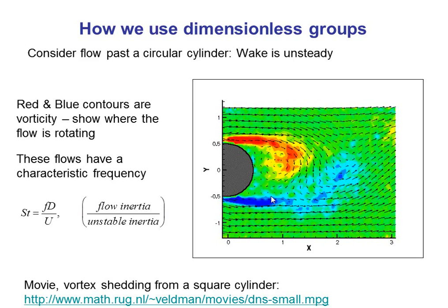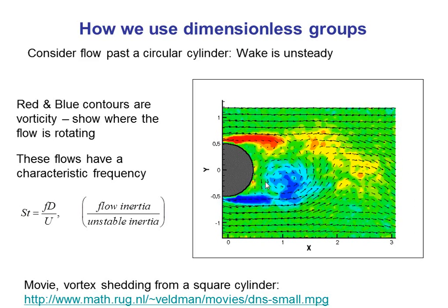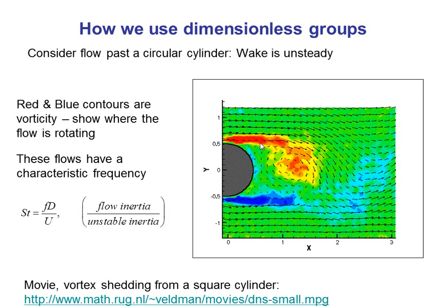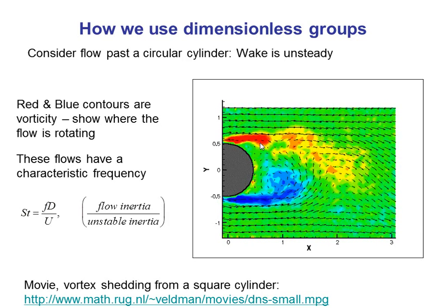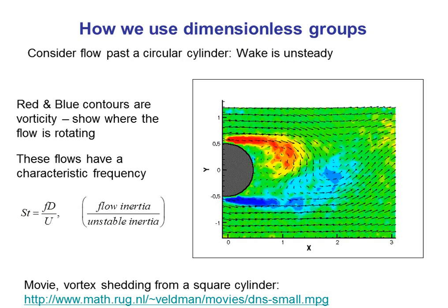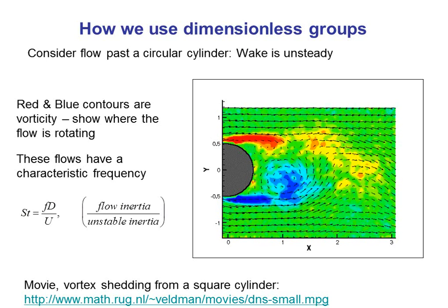No, not necessarily. Higher pressure normally in the front, lower pressure at the back. This red part here is where the flow is shearing. Flow is being swirled around, where high speed flow and low speed flow are close, the transition part. So that's shear.